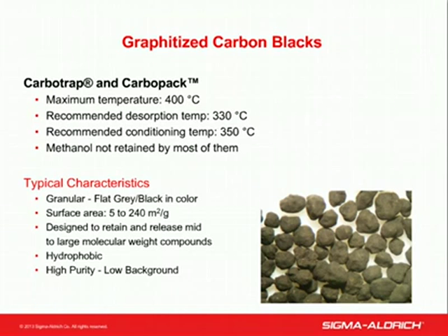All of the Carbopacks are very hydrophobic, so they're a good candidate when sampling high humidity environments. And graphitized carbons typically have fewer impurities than charcoals, making them more inert and useful for trace analysis. However, the carbon particles can be fragile, so you should try to protect the tubes from rough handling in order to extend their life.